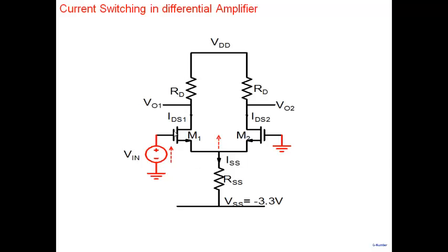Note that this voltage will travel like this through VGS here, so it increases this value here. So what it does is it reduces the value of VGS of this transistor. So when you apply a positive voltage here, effectively VGS of this transistor increases, while VGS of this transistor decreases. So in effect, drain to source current here increases and drain to source current here decreases.